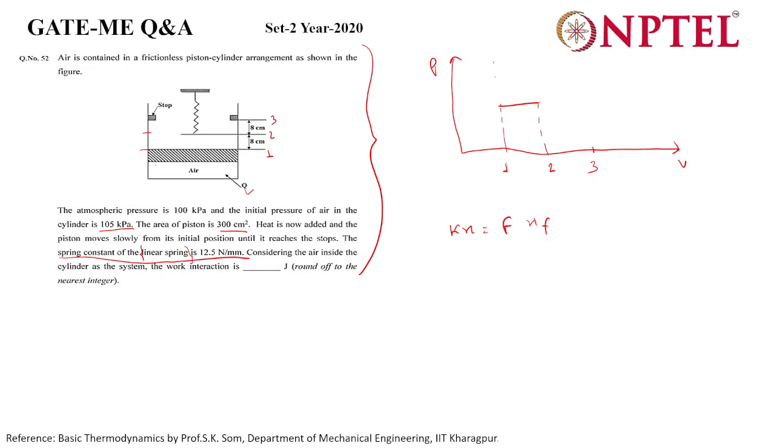So this force we can easily get, and we divide by the piston area, which is constant. K is constant, the total compression of the spring x is known, so delta x we will know. All would be constant, so the final pressure we would know, right? So the variation is linear, and what would be the final pressure from here?